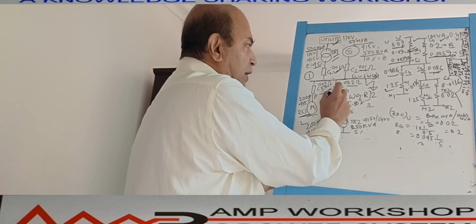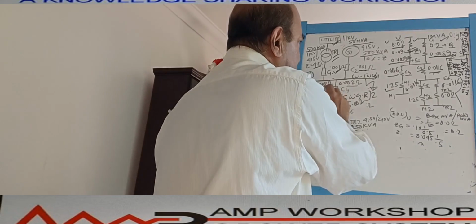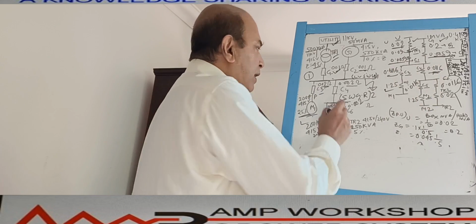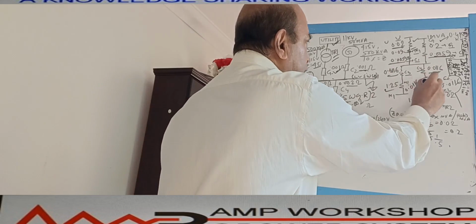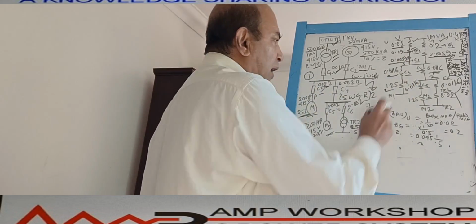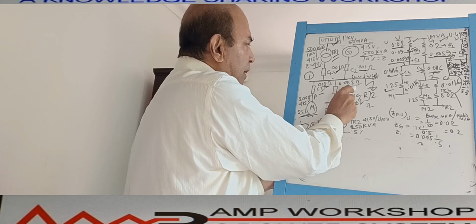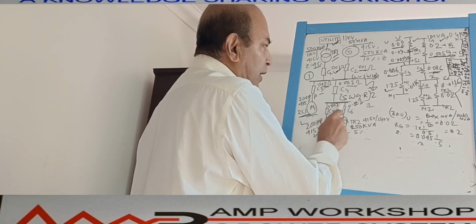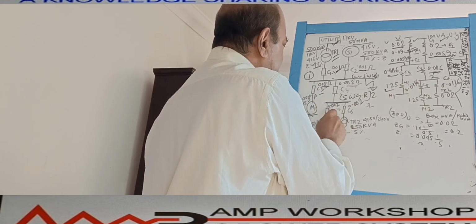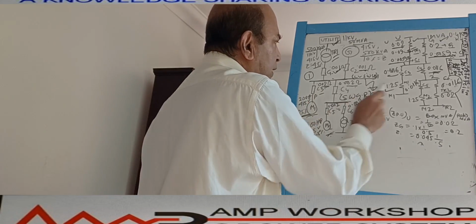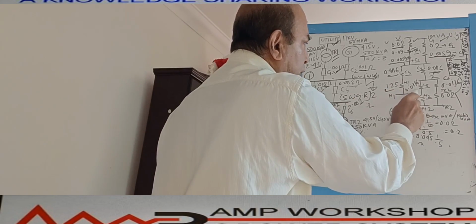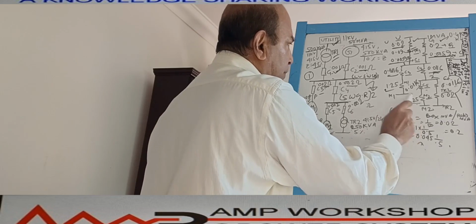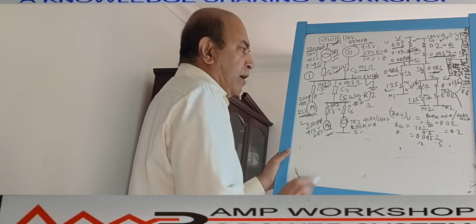So now the second branch here is the same, 0.002 is 0.0116. It is also 0.0116, same. Then it is coming to switchgear 2. This is the second switchgear. This is the first switchgear. Okay. Second switchgear. What is this cable? The same cable 0.002, that means 0.0116. Then from the second switchgear there is a cable. Same cable 0.002 ohm means it is also the same cable value 0.0116. This value we put over here. Then we have the motor. Motor is 1.25 per unit impedance.